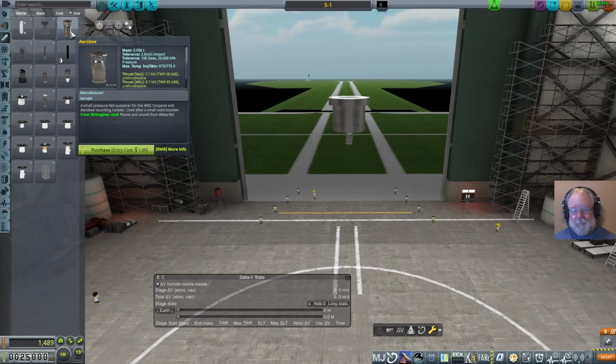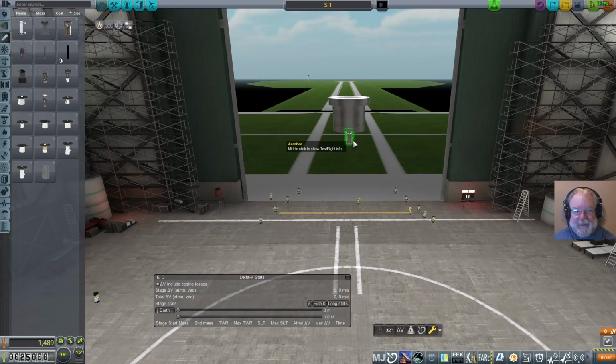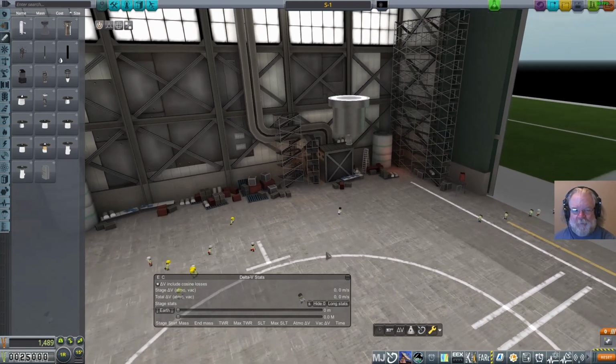So the fuel comes in. It's called ullage. If you're flying along and your nose drops below the horizon, the engine will probably flame out, because that bubble will probably hit there, because you probably don't have enough acceleration to make the bubble think it should be in front. Anyway, this is an engine that you start under acceleration or on the ground, and it keeps working as long as you're going up, and that's great.